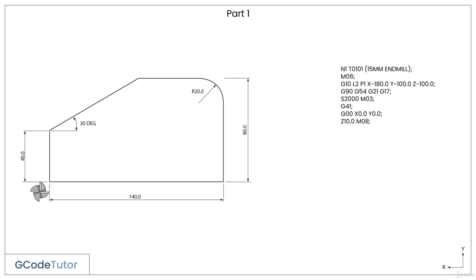I like to move the cutter down in Z on a separate line when we're under a G00 rapid command. This is so I can visually make sure that the cutter is moving safely inside the machine and missing any clamps or vices that may be on the table. So the final movement while in rapid is bringing the Z down, and the M08 turns on the coolant.